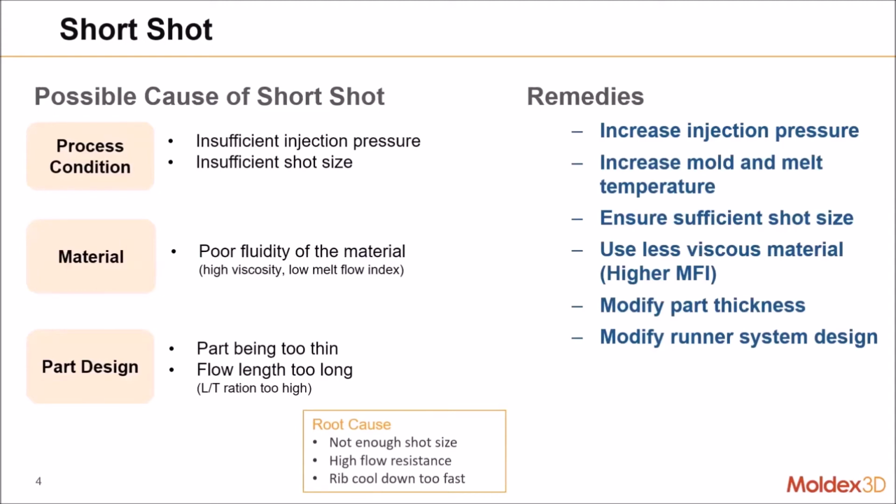And if we further categorize these causes into process condition, material, and part design. In process condition, it can be caused by insufficient injection pressure. So that means that there's not enough driving force to push the melt into the cavity. It can be insufficient shot size or stroke.